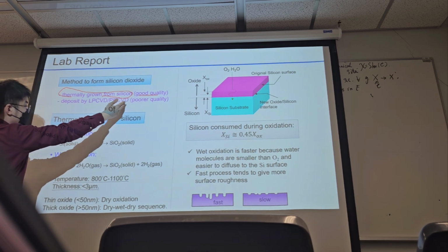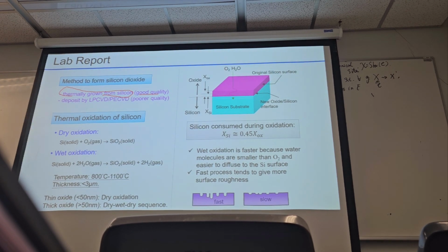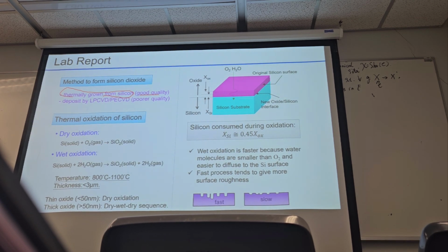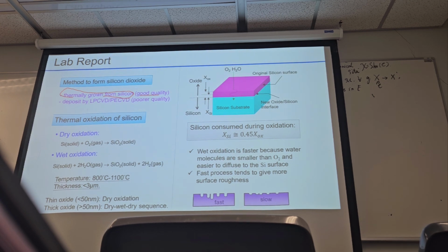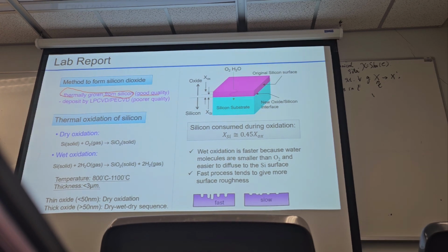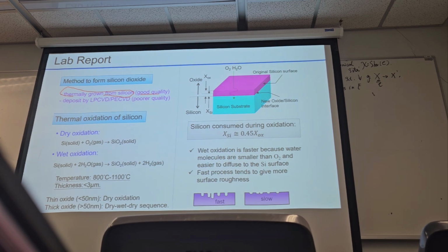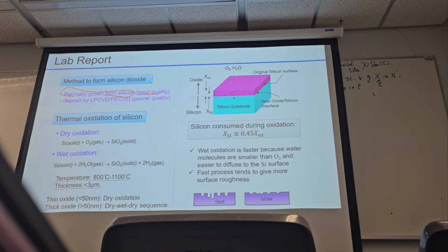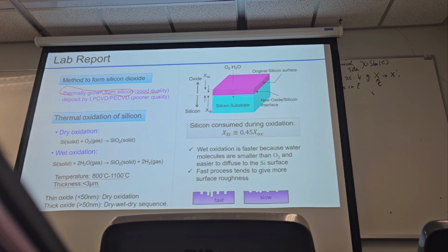While PECVD is the plasma enhanced CVD, which needs to be done in the chamber with activated plasma. And the required temperature can be lower because the plasma can provide the energy for the reaction. So for the PECVD, the temperature is typically below 350 degrees C, right? So I think you can go back to the previous slides to see the details.